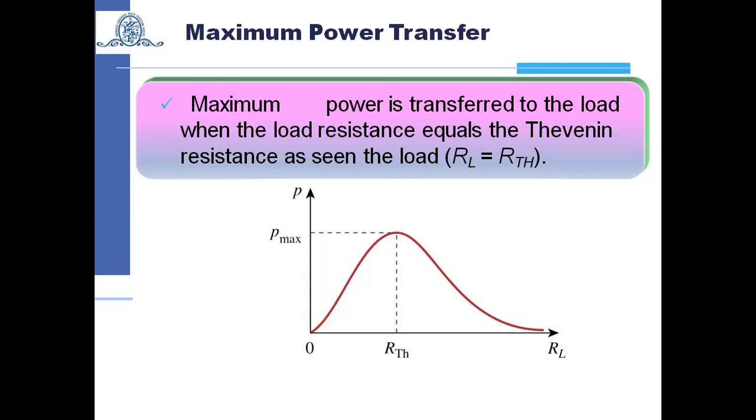For example, if we have a circuit that consists of impedances and energy sources, where a variable load is connected at the output, and we are supposed to derive the maximum power, you will get that maximum power value by using the maximum power theorem. The maximum power theorem states that maximum power will get transferred to the load if the value of load resistance becomes equal to the Thevenin equivalent resistance.